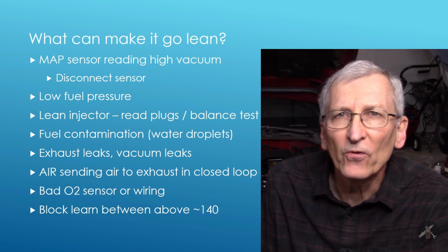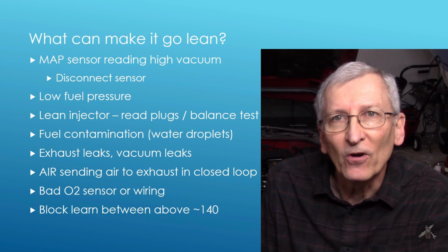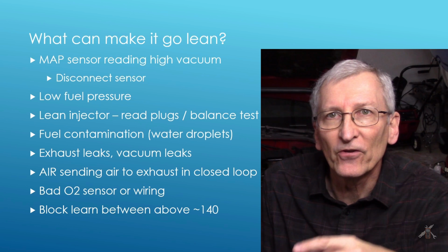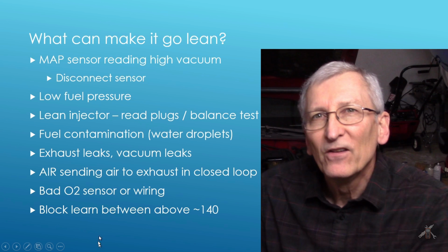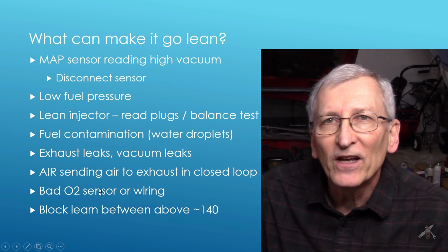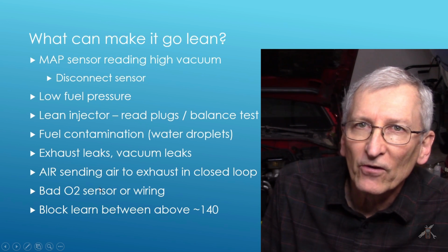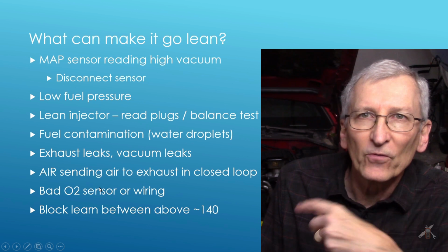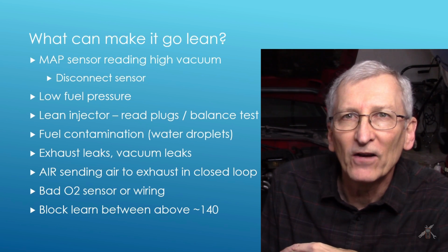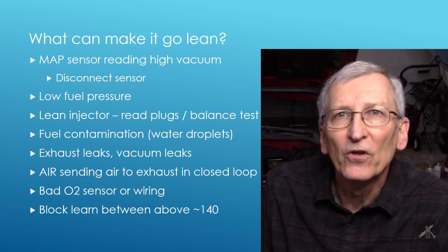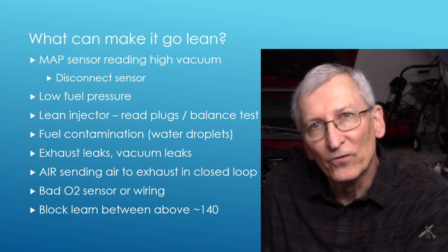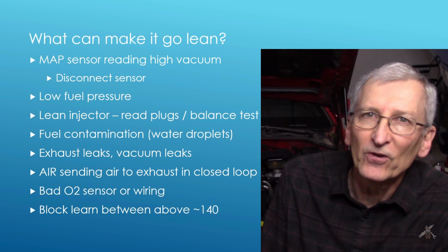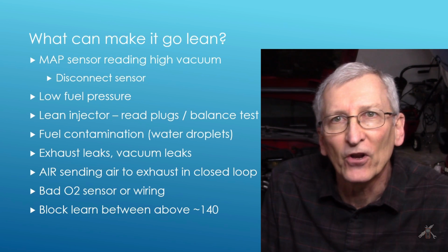Also, don't forget, in these old engines, if you've got a V, normally there's only a single oxygen sensor, and so right here, it's on the left-hand side, so it isn't reading what's going on in the right-hand cylinders. It's only reading the ones on the left. So if you have a cylinder doing something odd on the left-hand side, you read it on the O2 sensor. If it's doing it on the right-hand side, it's just going to go.